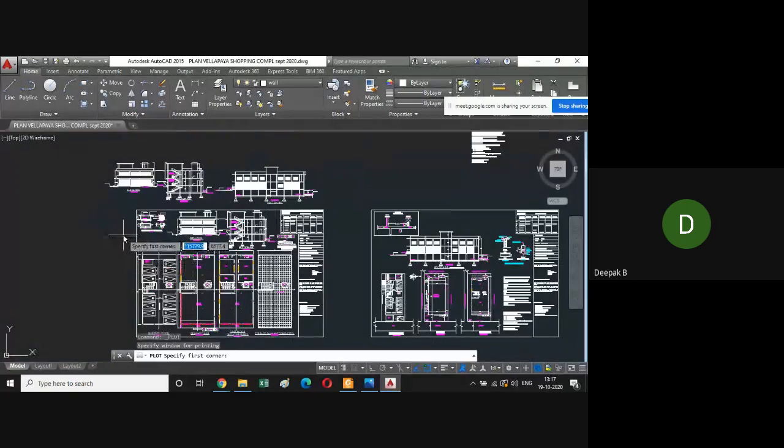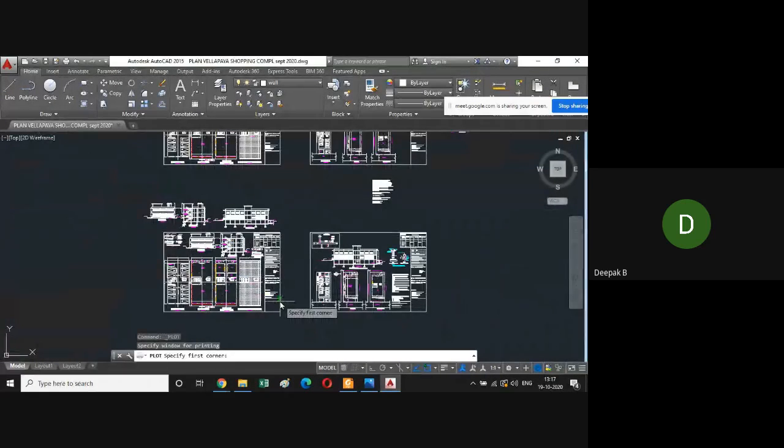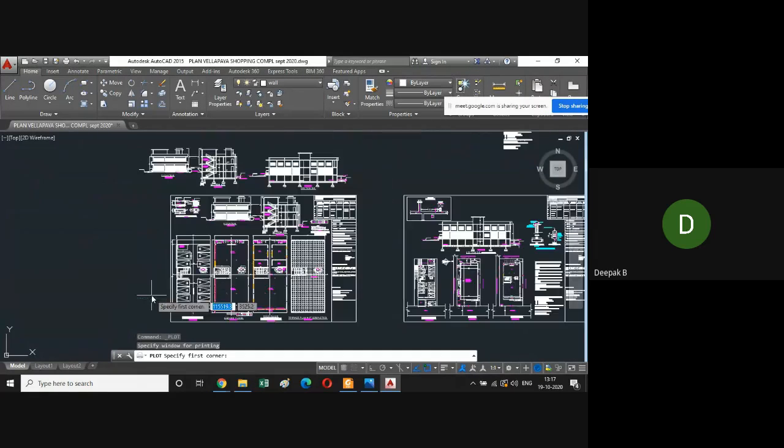Okay, we had selected window. What we are supposed to do is select a window. We will select a rectangle inside this, and everything inside that area will be printed. So that is the reason we have already drawn this boundary. I had already drawn the boundary here, and all the drawings are inside it.